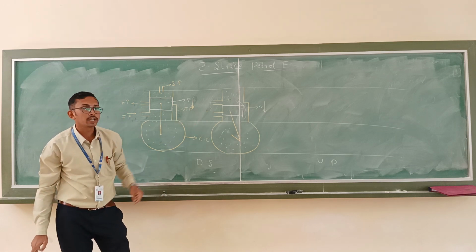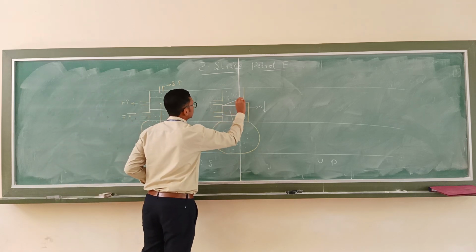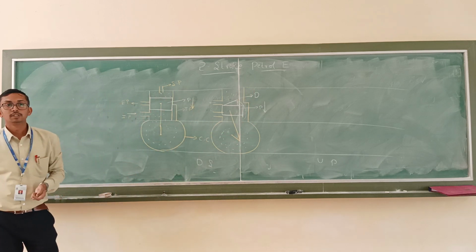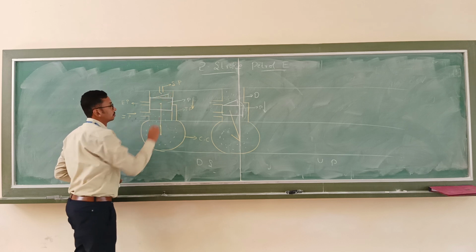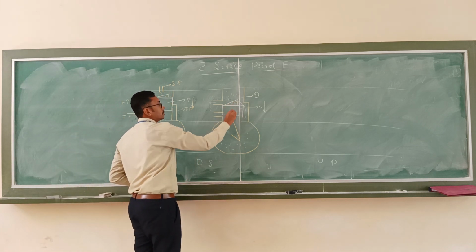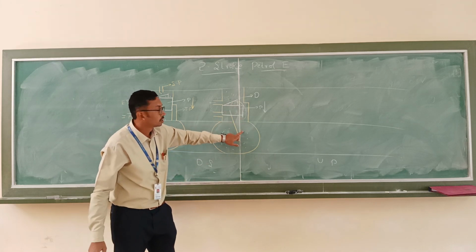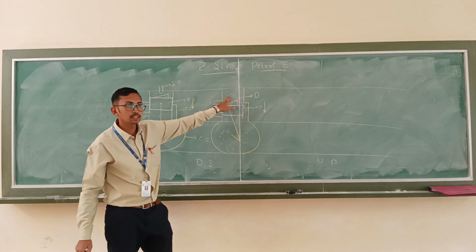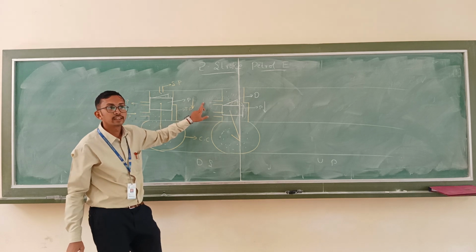Okay, I am going to write another part. You have to tell me what is the reason for this. This is called the deflector. What is the purpose of the deflector? Can you tell me? See, if this deflector is not there, the air fuel mixture from the crankcase is going to enter the cylinder and directly go to the exhaust.